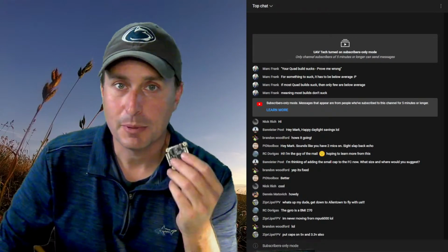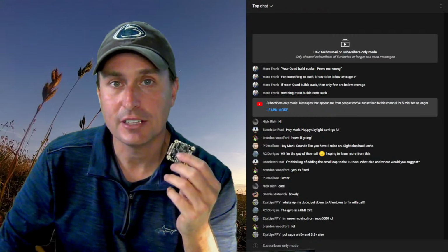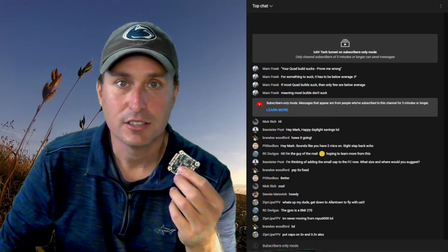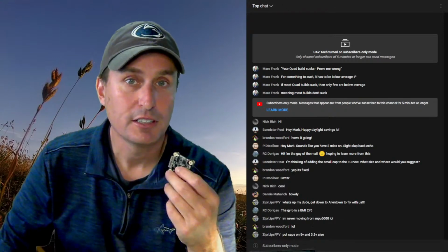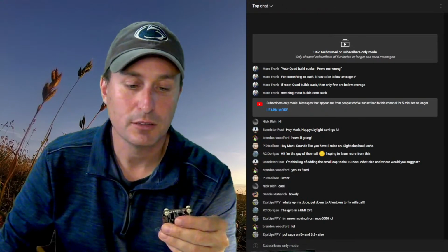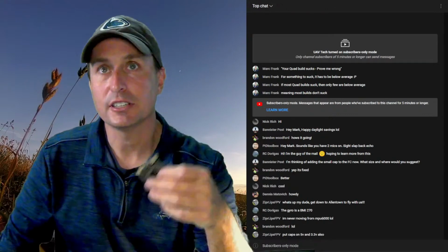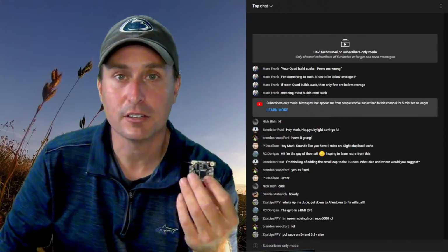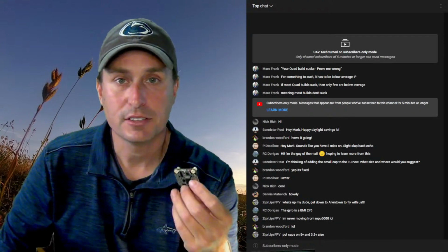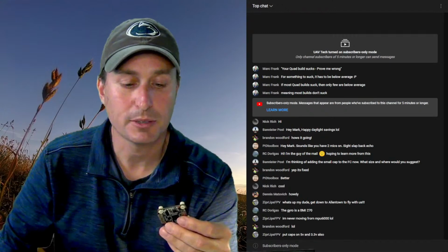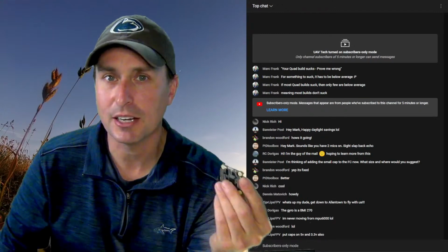So you could put a capacitor directly on that, but you have to have a low voltage capacitor, 3 or 5 or 6 volt. It could be electrolytic, tantalum, or ceramic. The electrolytic have a lot of microfarad rating, whereas the ceramic and the tantalum typically don't have as high microfarad ratings. I believe, but I'm not an electrical engineer.